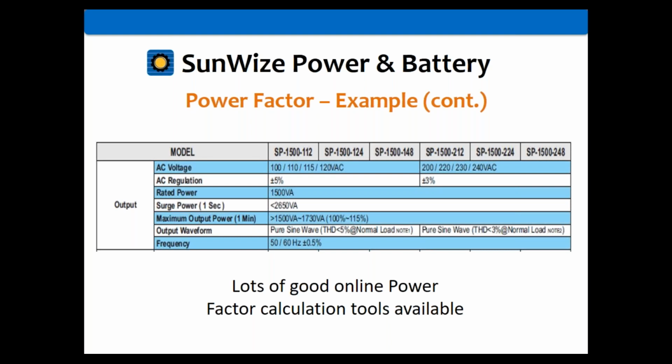Is it going to be big enough to support that load? And it does matter. I have in the past had a couple of loads that caused me issues. I had one that was a telecommunications site that had a horrible power supply for the radio equipment that ended up giving me a power factor of about 0.5.